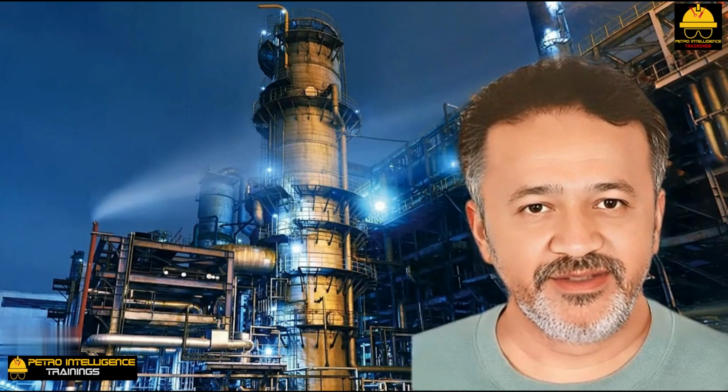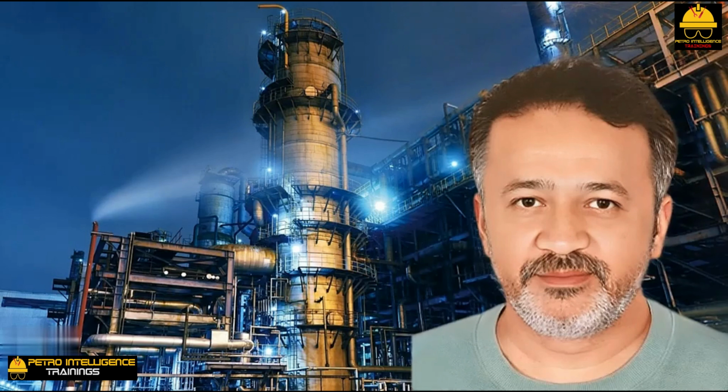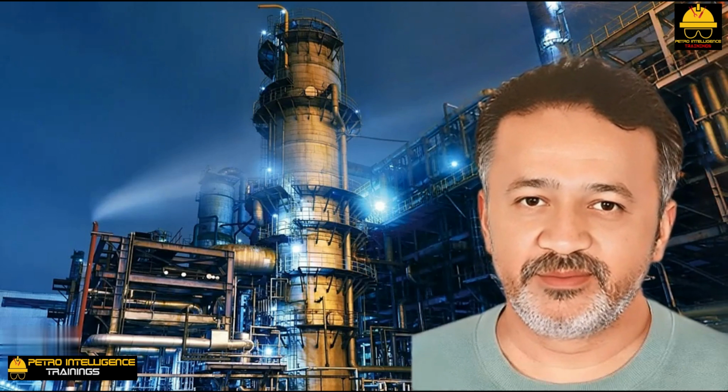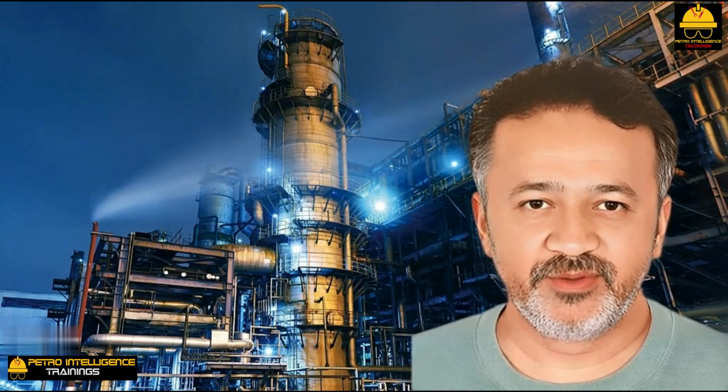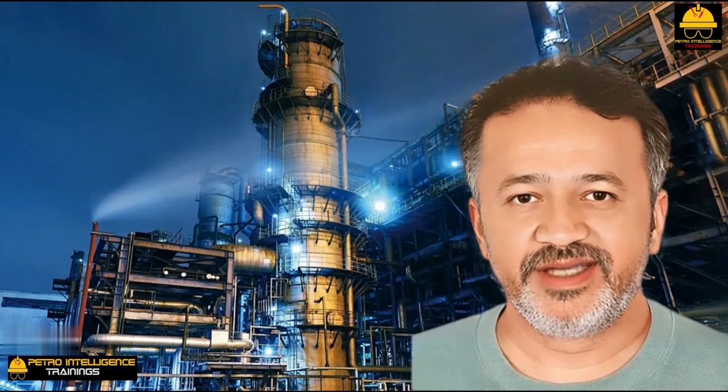What is air lock? Vapor binding, or air lock, is another common cause of household radiator malfunction. Often, the vapor accumulating in the radiator is CO2 rather than air. The CO2 originates from the thermal decomposition of carbonates in the boiler. Regardless, air and CO2 form a non-condensable vapor in the radiator. These non-condensables mix with the steam in the radiator.